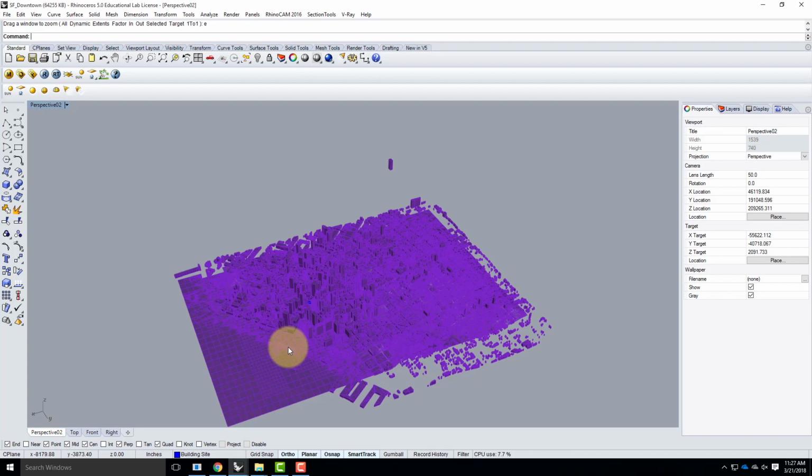Now, when I do the renderings of this particular building, rather than have photorealistic surroundings, rather than have all the buildings around it perfect, I'm just modeling those as abstract white objects. So all of this purple area, I'm going to apply a generic white texture to. The texture I like for it is white porcelain because it has a little bit of a shine to it, and I think it ends up looking pretty good in the renderings.